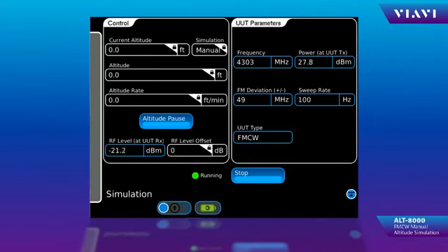If you were using couplers and you had good transmit parametrics and you believe there was a problem on the receive side, you could disconnect from your couplers and then go direct connect to the rad-out under test to determine if it's a problem in the antennas or the coax. If everything works by direct connect, then you know that you have a problem in the coax or the antenna. You can troubleshoot those and then retest. If the test doesn't work direct connect, then the problem is in the UUT, and you can continue with the replacement of the UUT.